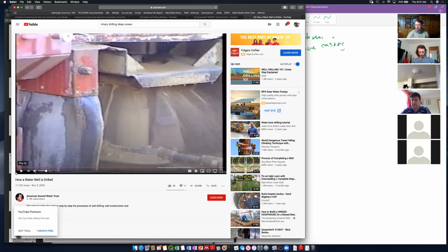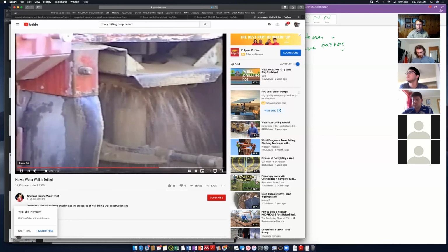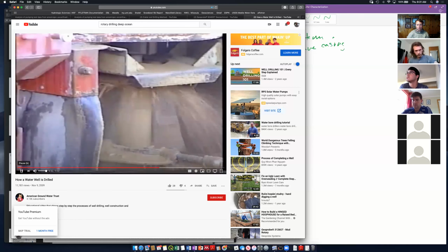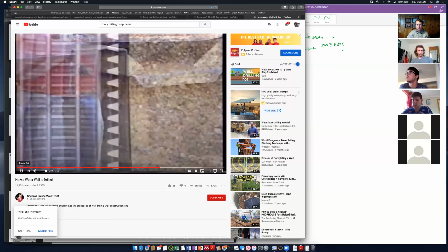The idea is just to get clays and drilling mud pumped out and pushed away from our screen. All right, so developing a well, you just pump it really hard or inject, and you're just trying to wash out as much of this clay from the drilling process as possible, to remove fragments and stabilize the area immediately adjacent to the well intake. This is called developing the well.